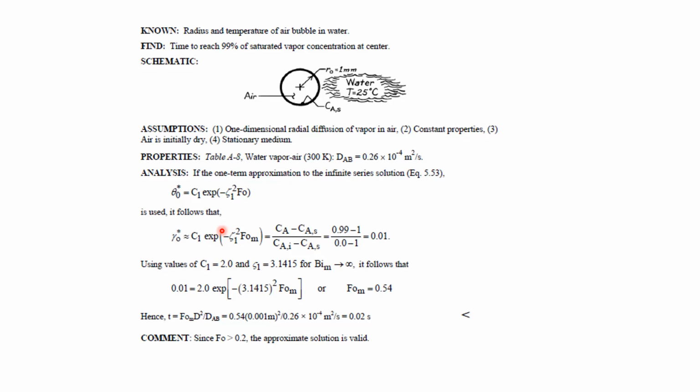So the question is that Fourier number is less than 0.1 in heat transfer. And suppose we are keeping a sphere, allowing it to cool in air at a particular temperature higher than the air, maybe 60 degrees Celsius. So gradually the sphere will get cooled down. So in that analysis, we will first check Fourier number to be less than 0.1 for the analysis to be valid. So if not, any idea of that? What type of analysis is that?